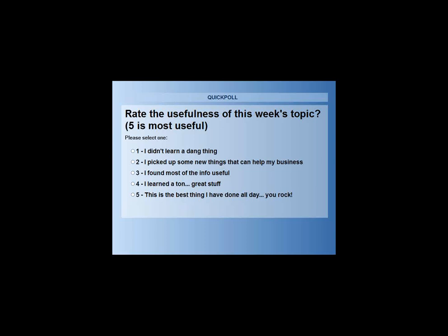Joe also asks, are the factory program VFD set points field adjustable? Yes, the VFDs can be adjusted from these manufacturers in the field if you need to. Generally, you don't, because there's not much you can do differently. But let's say they set it at 67% and you really felt you needed to have it at 69%, you could go in there and change that. Obviously, you can't go less than the CFM that is required for the cooling capacity, which generally needs to see about 350, 400 CFM a ton or so.